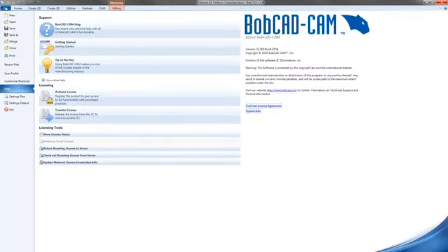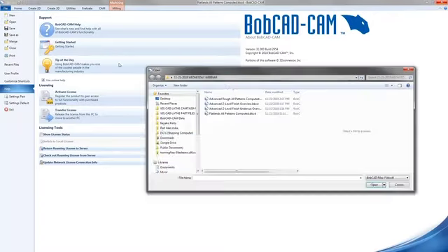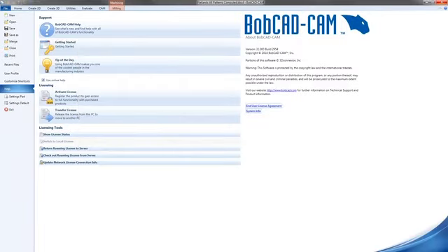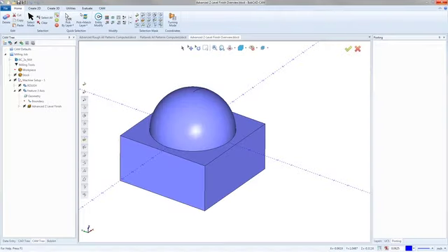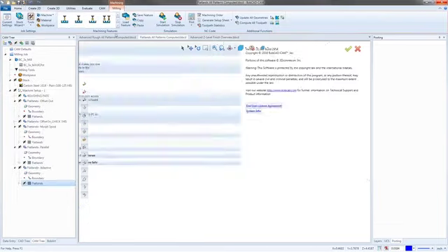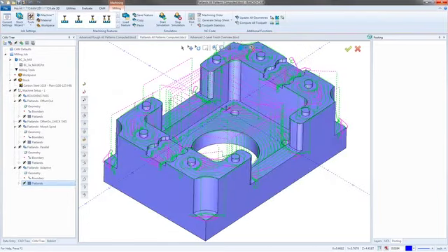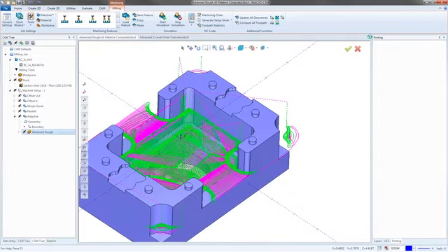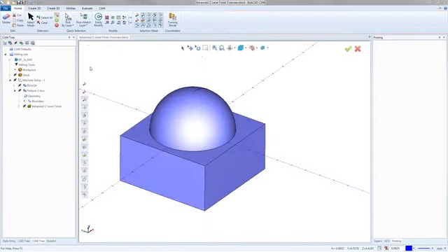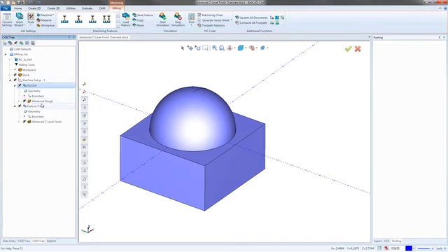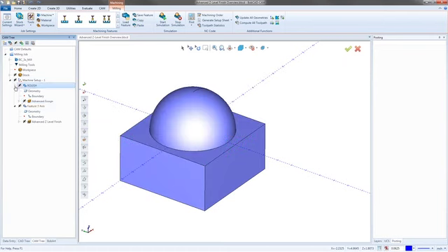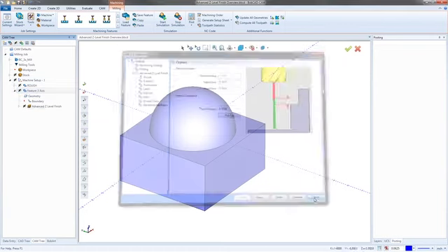All right, now on to the good stuff. This is something I was playing around with, and I don't get to use this toolpath very often where I get to do undercuts. So I'm going to talk about the advanced Z-level finish. Let me just save this and get it out of my way real fast. All right. So I have a roughing toolpath on here, and all it's doing is going in and just taking the material down.